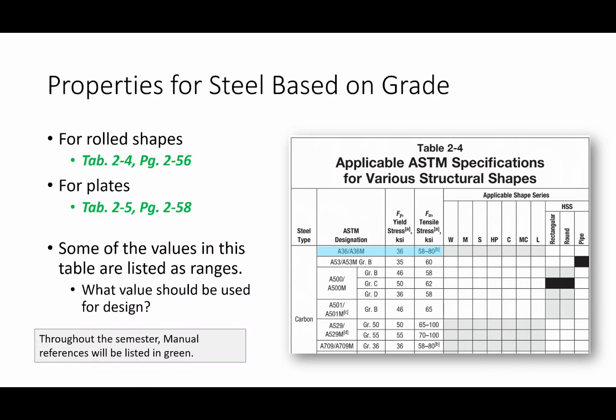So the thing about steel is that when you start upping the strength, you start lowering the ductility. Now ductility becomes really, really important whenever you have extreme event loads, and a good example of an extreme event load is an earthquake. Now in 1994 there was a big old earthquake, the Northridge earthquake, in the California area. And before then, back in like the 70s and 80s, the steel industry was strongly advocating moment frames for all of their seismic structures.